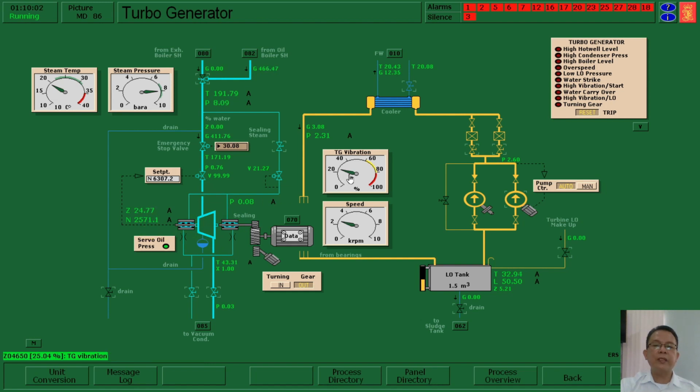and we can find here our vibration meter is going down. So we can adjust it or increase it into 40%. By 40%, the opening of our emergency valve is almost half. Still, the revolution is increasing, and it is nearly at the set point. And we can look here at the vibration meter. Does it move? If it is slowly going down, then we can put it into 50.